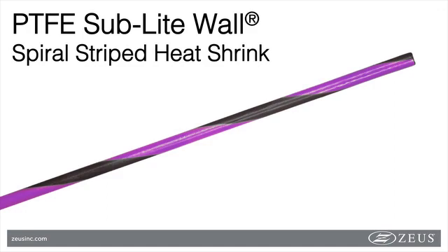Snares and forceps shafts can be encapsulated using PTFE heat shrink as electrical insulation. PTFE heat shrink benefits both the device and the patient by providing electrical insulation, a lubricious surface, and moisture protection. Laparoscopic instruments are an example where FEP heat shrink can be used to coat the outer shaft, allowing for insulation between the patient and the device as it cauterizes tissue.